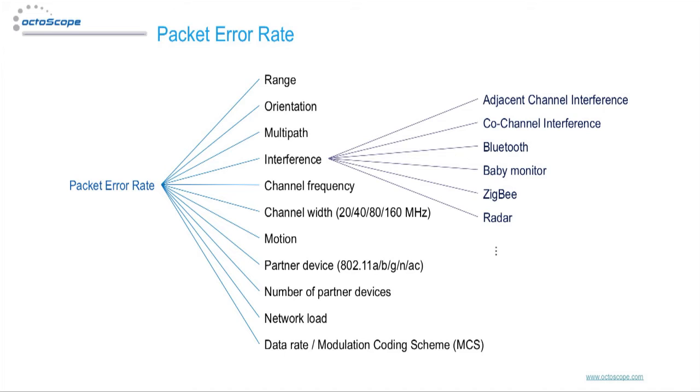Low packet error rate is important for services such as voice, video teleconferencing, and automotive DSRC communications. Such services send short packets that result in low throughput, and hence throughput is not an appropriate measurement here, but these packets must be reliably received for high quality of service to be achieved.